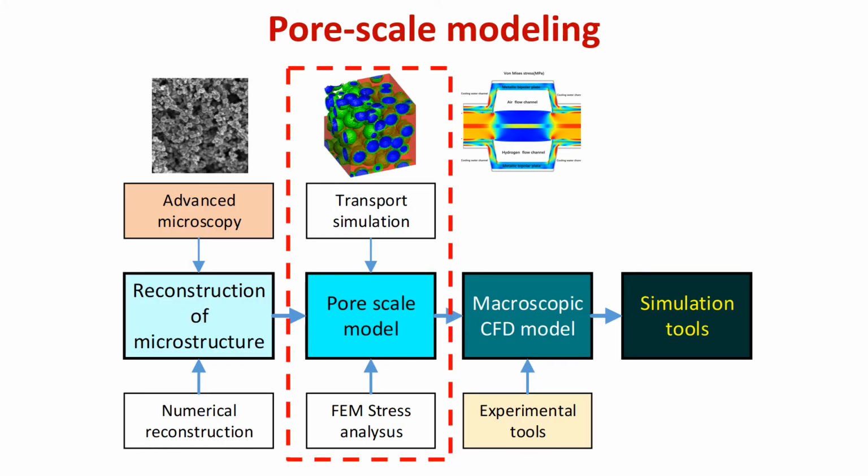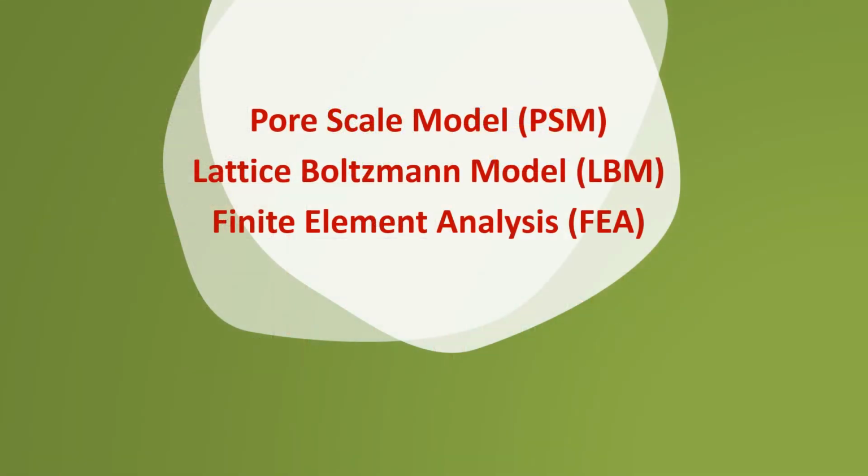Now we come to the pore-scale modeling, which involves different methods to compute effective transport properties as well as the solid mechanics of the material under external forces. So I'm going to briefly talk about these methods and show some results. These models are the pore-scale model, lattice Boltzmann model, and finite element analysis.